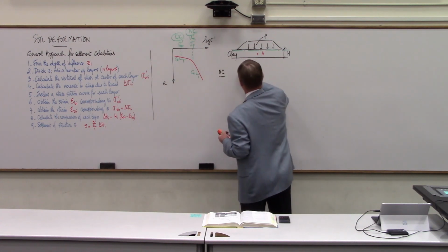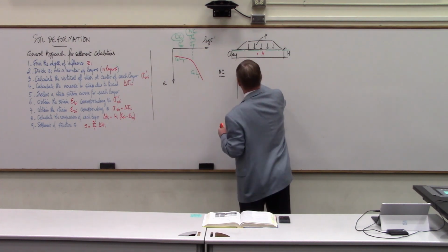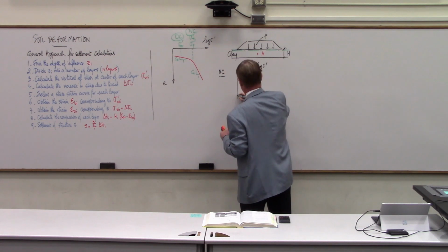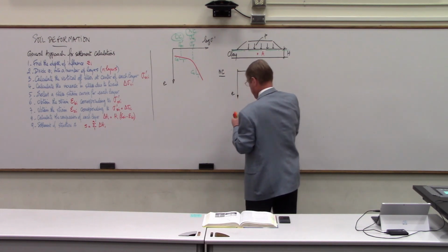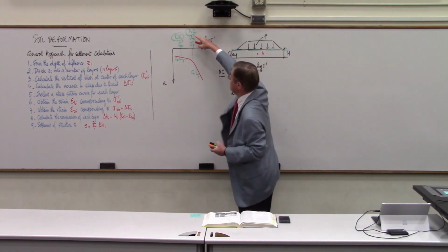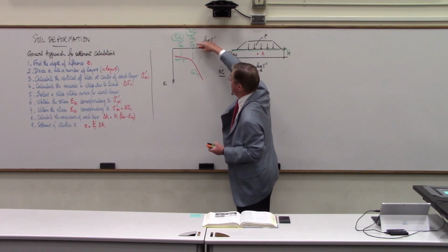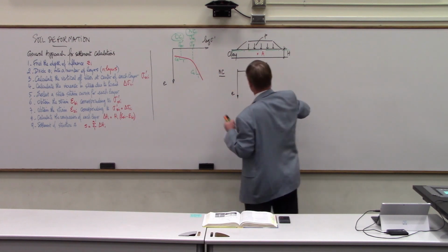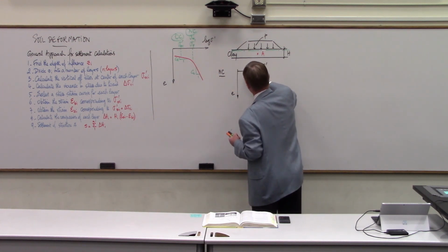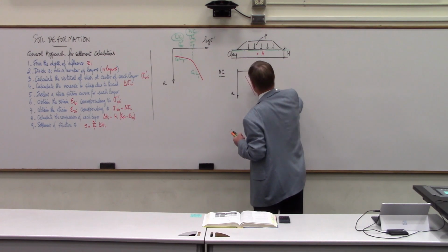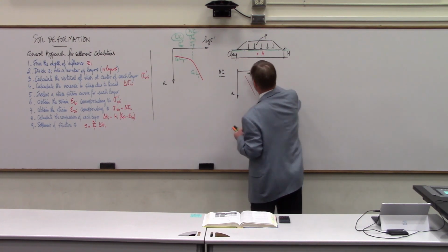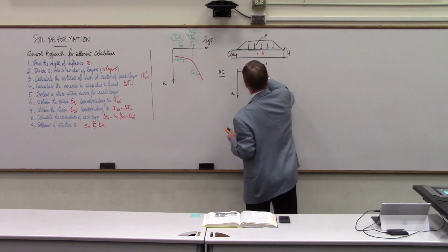In the case where the material is normally consolidated, this curve looks like this, log sigma prime E, and sigma prime OV is equal to sigma prime P. The curve actually starts right here. So this line is one single line, and the pressure right here is sigma prime 0V.